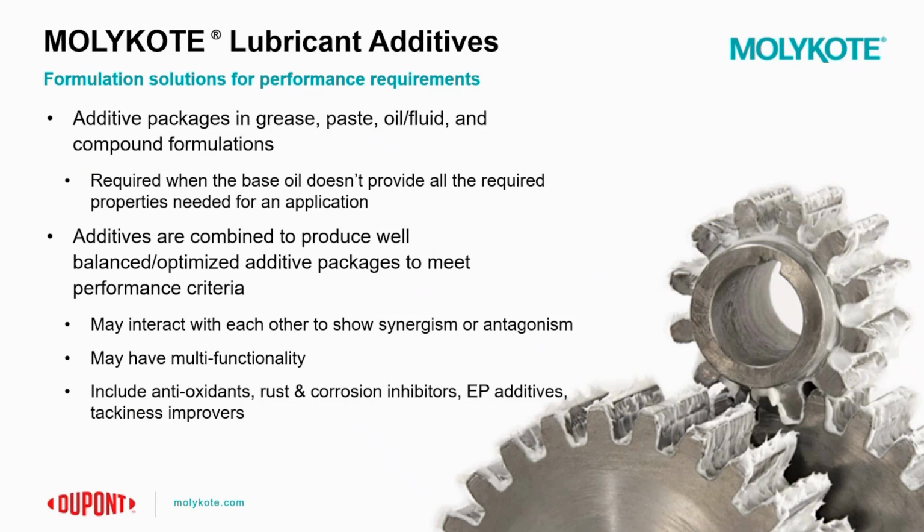Since lubricants are formulated to fit a diverse range of applications, different lubricant technologies, like different types of product families, will often use different combinations of base oils and additives. Since base oils alone rarely satisfy all the required properties of a lubricant, additives can be used to amplify the favorable properties of the base oil and potentially mitigate some of the unfavorable properties of a base oil.